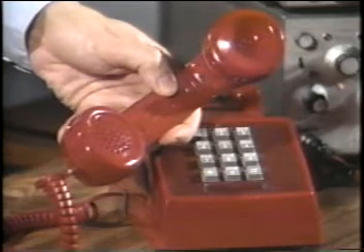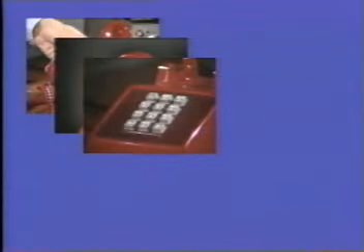Briefly, we have reviewed how a typical telephone can request the use of the telephone switching system by simply lifting the handset, indicate that the switching system is ready for use by receiving a dial tone, generate and send the number of another telephone when the caller rotates a dial or depresses a keypad, indicate the status of a call by receiving tones such as audible ringing or a busy signal, indicate an incoming call by ringing a bell or some other device, convert acoustic energy into analog electrical signals for transmission, and then convert analog electrical signals back into acoustic energy, and signal the system that a call is completed when the handset is placed on hook.